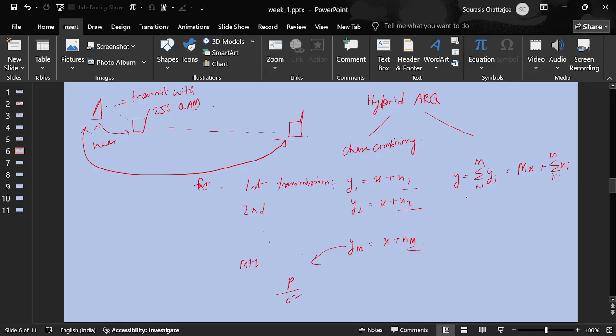Okay, so channel capacity will be high. Channel capacity will improve, true, but we are working towards improving the SNR, right? Because only when SNR crosses a certain threshold am I able to decode what is being transmitted. And currently this P over sigma square is less than that arbitrary threshold which is required for 256 QAM. So how does this Y help in mitigating that effect?